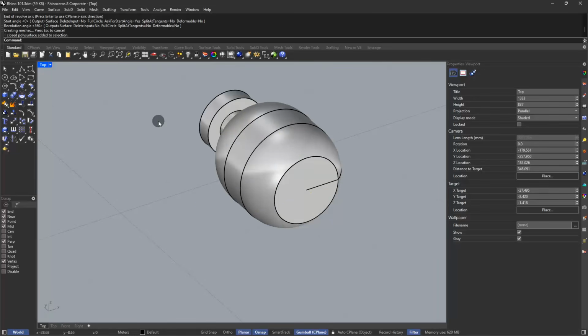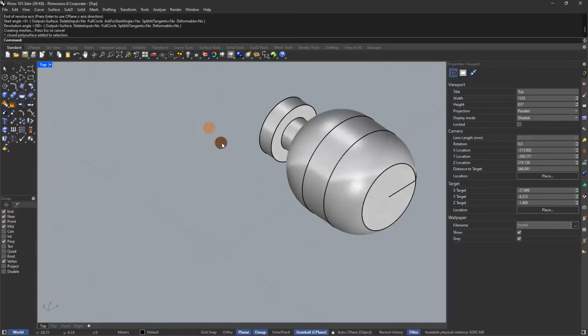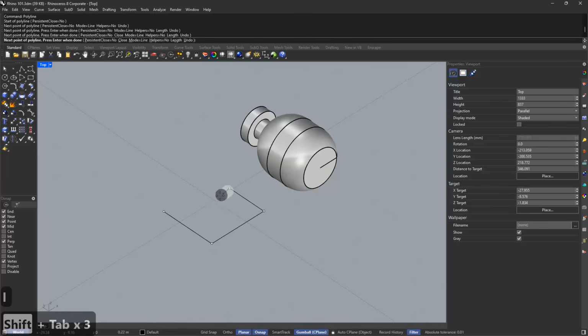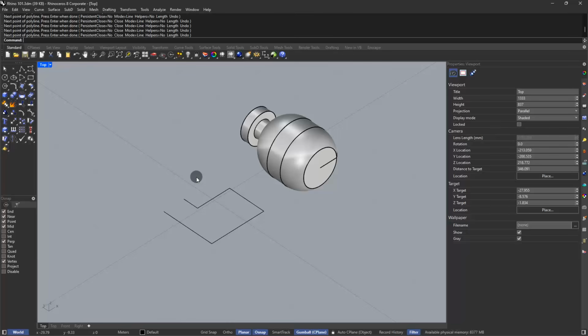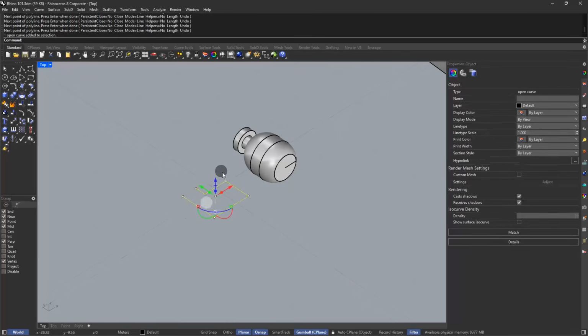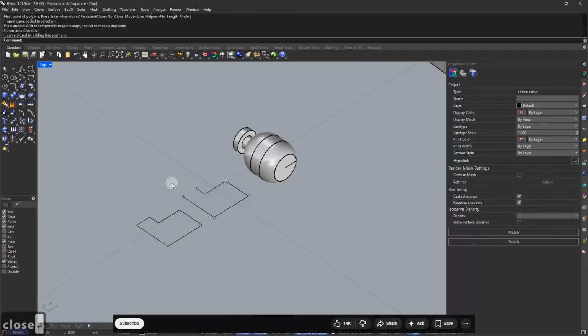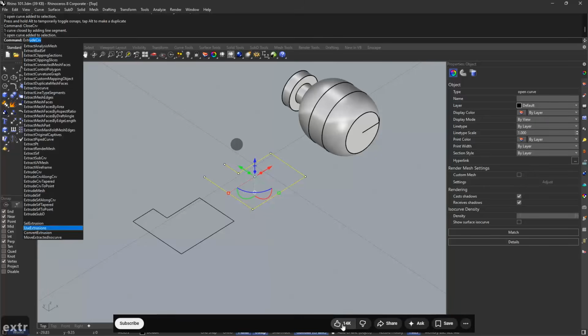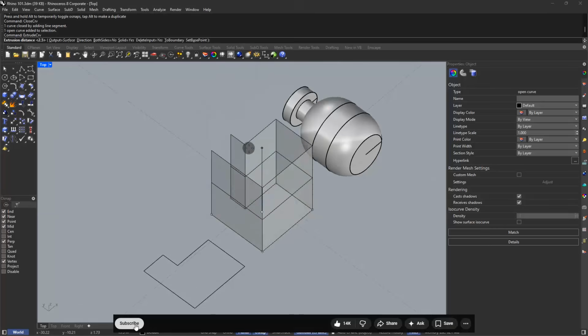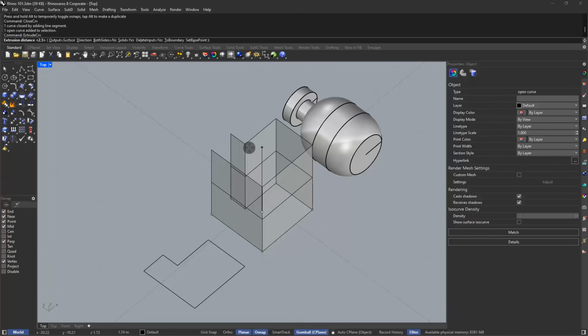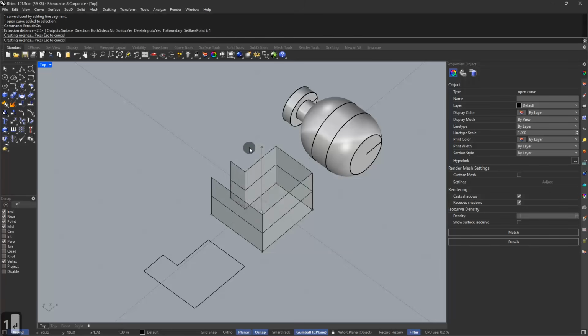The next command is extrude. We used it before. For example, if I have a poly curve like this, it can be an open curve or a closed curve. So I will copy this and I will close curve. So you can extrude curve, and because this is an open curve, it will extrude it like this. You can specify your extrusion distance. For example, I use 1 and press enter.